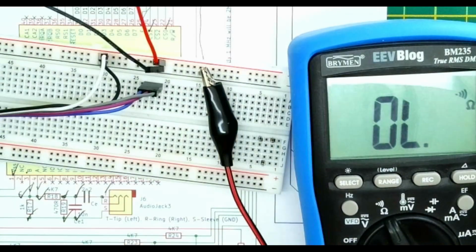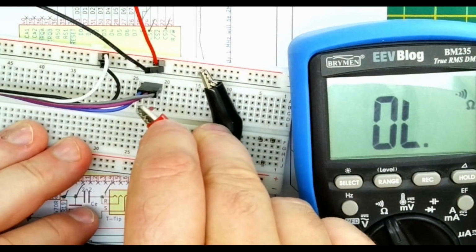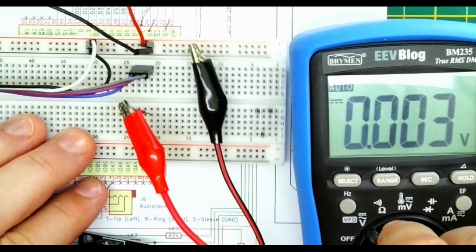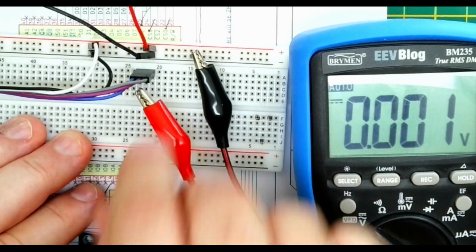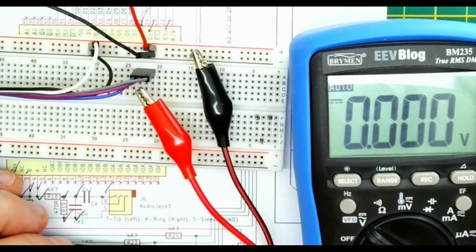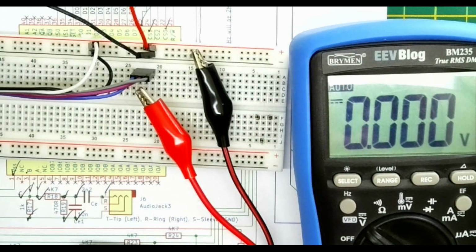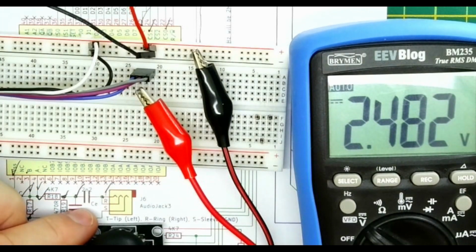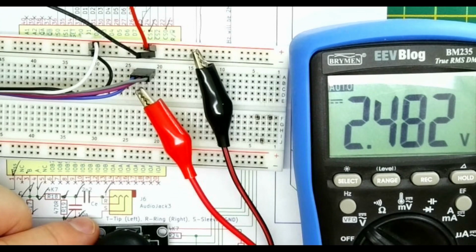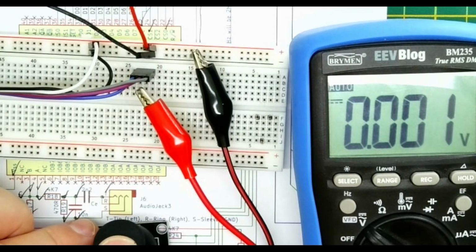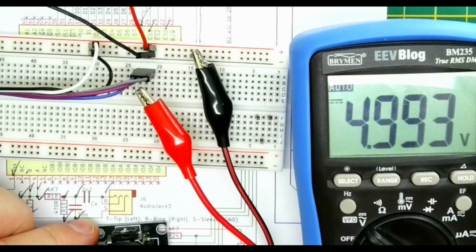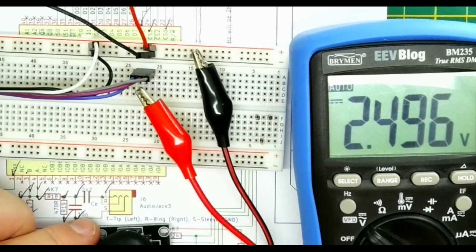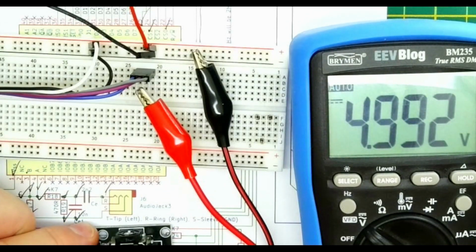Then the easiest thing to look at here is to just plug in some power, and put the voltmeter on volts, on purple, which I think by default is the vertical. Just switch on the power, so it's only set to 5 volts. We can see on the meter that in its neutral position it's just under 2.5 volts. If we push it up to the top, it goes down to 0. If we put it down the bottom, it gets close to 5 volts. So it starts in the middle at about 2.5 volts. Up is 0, down 5 volts.